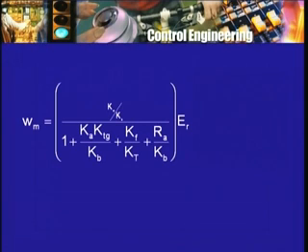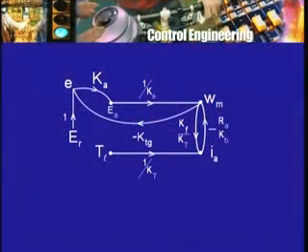So that's the expression that multiplies the reference voltage. What about the expression that multiplies the load torque? Now what is the forward path from the load torque node to the speed node? TL to omega m. Once again there is only one forward path, TL to Ia and Ia to omega m. And as I had anticipated earlier, in this path there is a negative sign, which I told you we expect, because if the load torque increases we expect the speed to decrease.